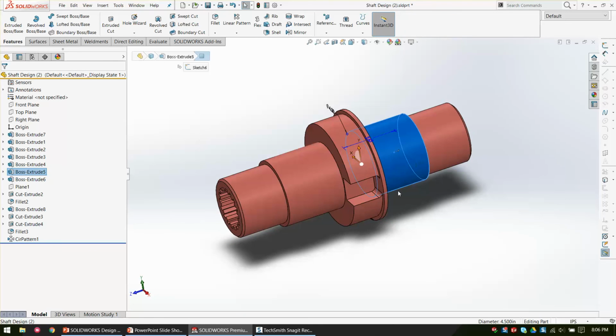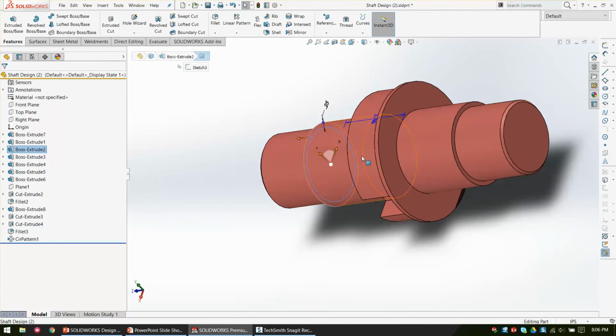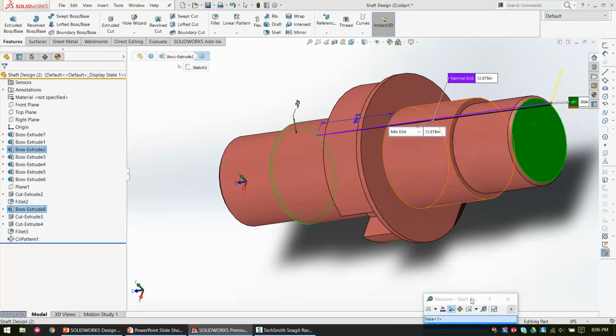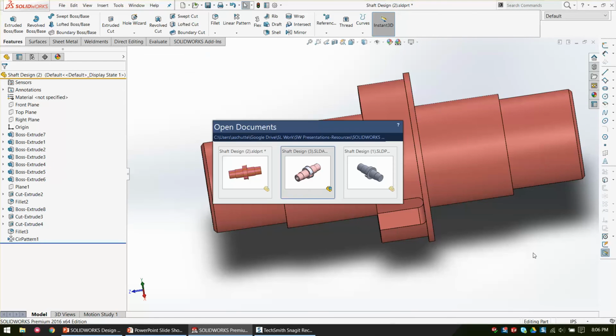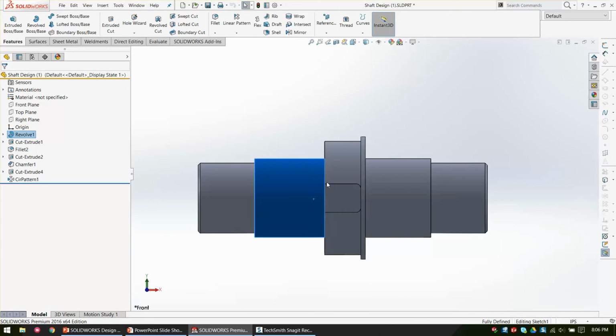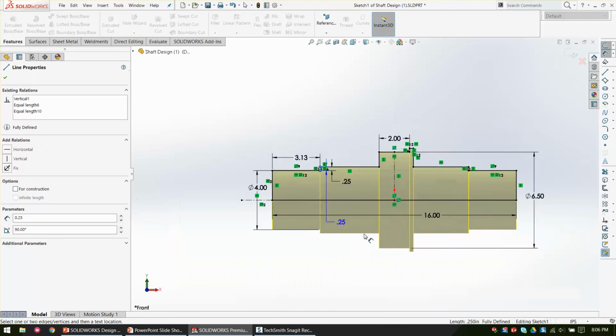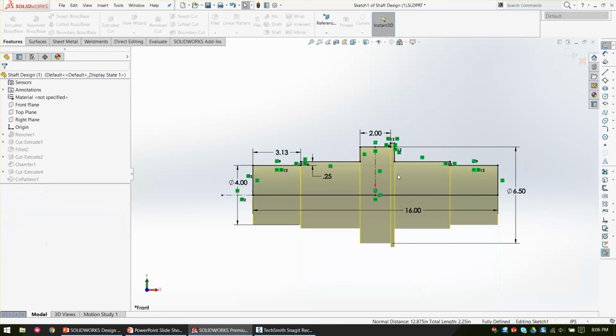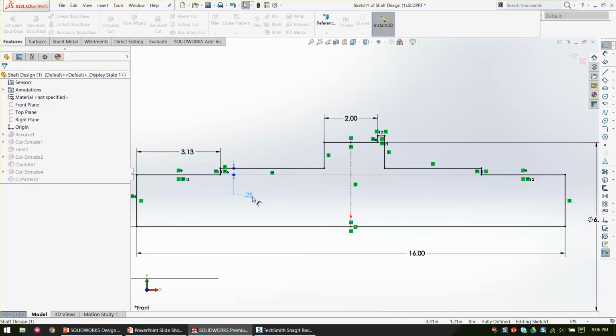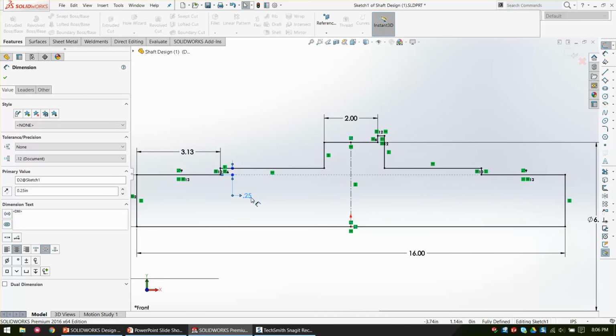But the other thing that we struggle with is if I want this surface to always be 1275 from that top, you can't do that with layer cakes very well. But in our revolve model, I can very easily grab this, and this will overdefine it, but I can very easily grab this and say that's always there, and everything else is going to move. But the really cool thing about this model is the customer decided that a 1/4 inch on the radius, or 1/2 inch on the diameter, was the magical dimension for the retaining lip to hold our bearings and our sprockets.